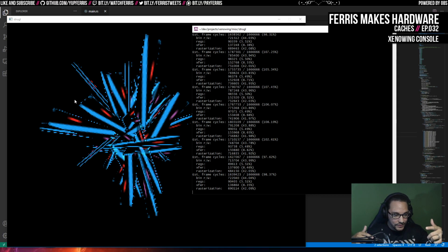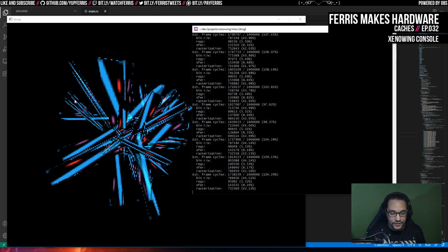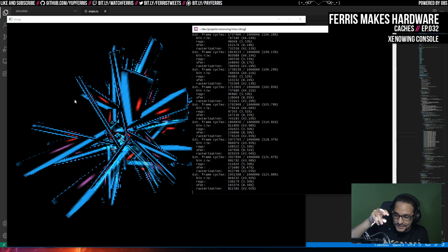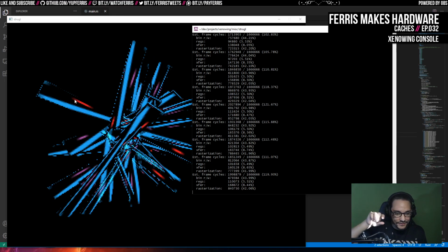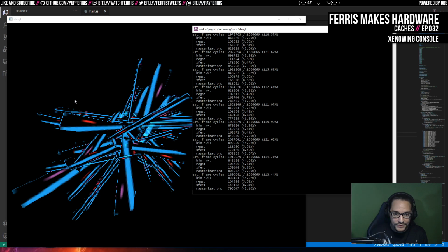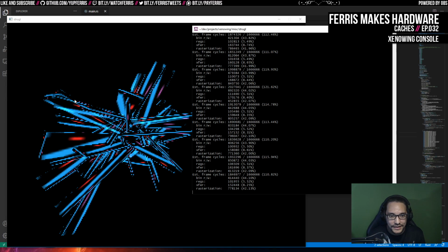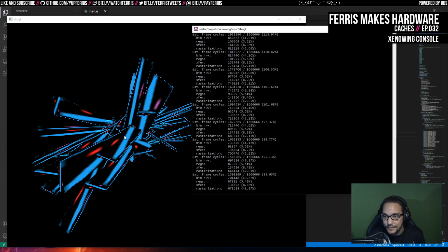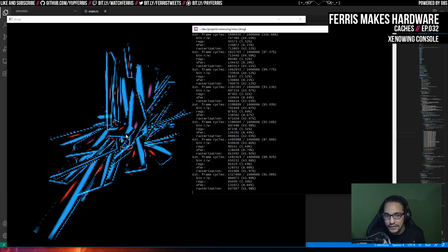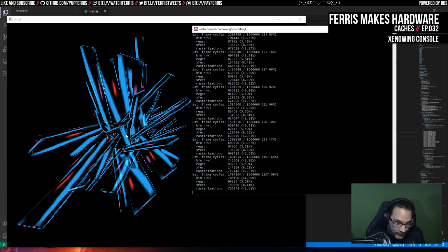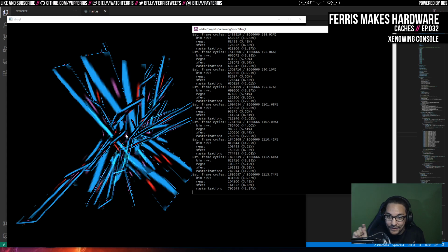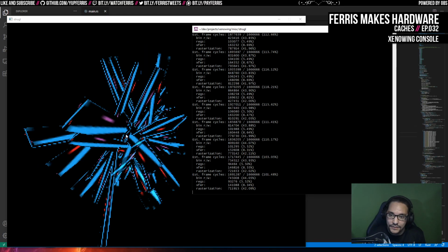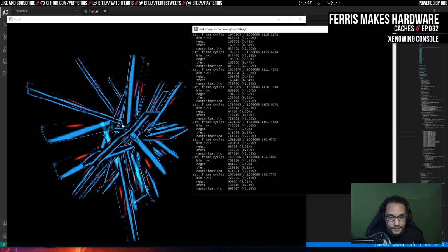There is another level of that, which you also might be talking about, where you can do Morton ordering or something else with the actual data, on the next level up. So yes, I'm putting the 4 in different banks, but in addition to that, you can also support a better local order. So maybe that's what you meant. Yeah, totally. So yes, I want to do both. Right now I only bank the memory. But what you're talking about is swizzling the textures, which will also improve cache locality, which is definitely something I want to do. But I haven't done it here because it doesn't matter yet because it's all in local memory. But again, when I change this to a real cache, that will definitely help.